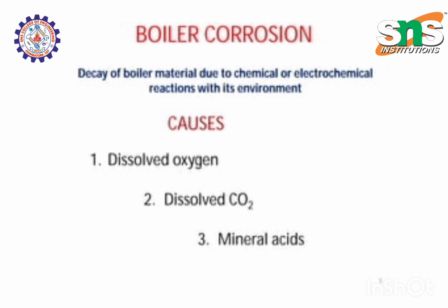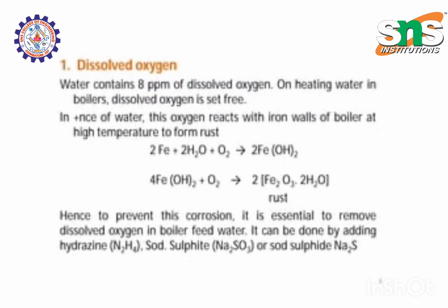In the chemical method, sodium sulfite and hydrazine are some of the chemicals used for removing oxygen present in the water. Hydrazine is found to be an ideal compound for removing dissolved oxygen in water, especially when compared with sodium sulfite. Hydrazine is best, since the products are water and inert nitrogen gas, so the byproduct is also easily removed.